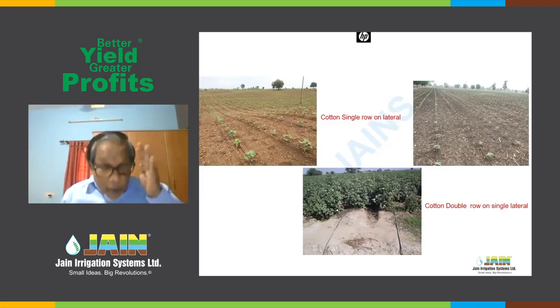The main problem is this, not even the soil. The main problem is that in the initial stage of growth, the root system is not spreading laterally much, it's going deeper, so it cannot get into the moisture zone if you put one drip lateral. That's the point.